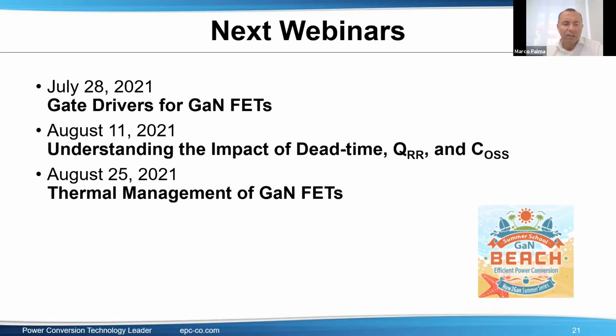The external layers, the top and the bottom, are usually 1 ounce because our devices are chip scale devices with small bumps, and PCB technology doesn't allow the required precision with 2 ounces. So the top and bottom layers are 1 ounce, but the internal layers are 2 ounces.